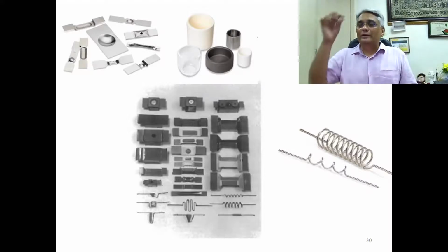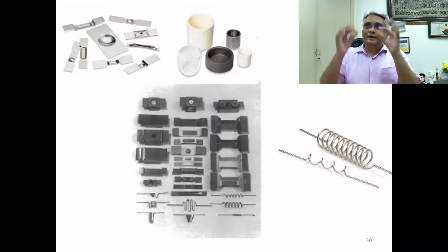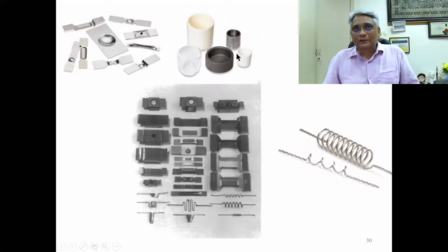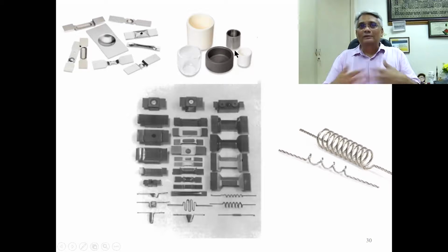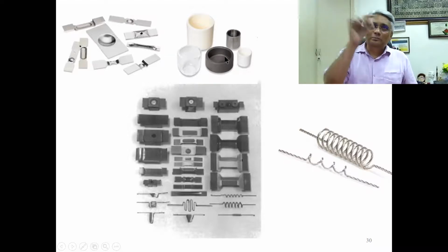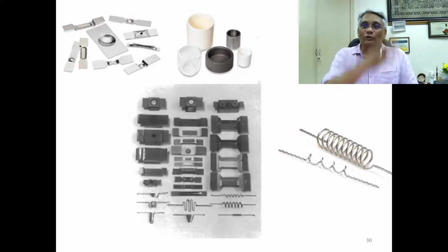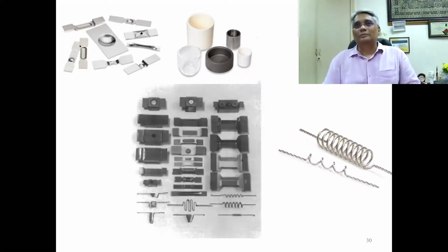Imagine if I have a high energy source and I make the high energy impinge on a crucible which you fill with a given material system that needs to be deposited. I'm not heating the entire crucible and melting the whole thing. With a radiation source, I should be able to melt only a part of it, which means I'm not making the melt flow around inside the crucible.